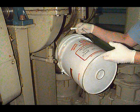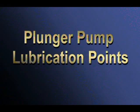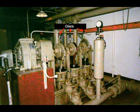Lubrication of the plunger pump will have to be done in accordance with your manufacturer's specifications and schedule. Here are some of the points of the plunger pump that will require lubrication. 1. Eccentric connecting rod. As shown earlier, there is an oiler mounted on top of the eccentric to provide adequate lubrication to the connecting rod eccentric bearings. After initial operation, the oiler is usually set to provide 2 drops of oil per minute.